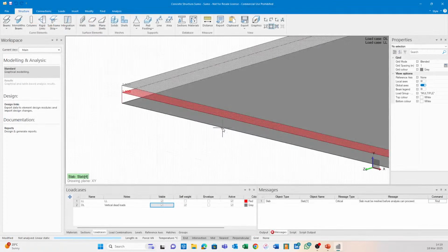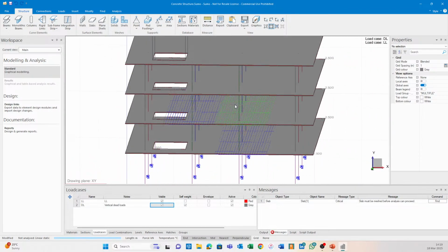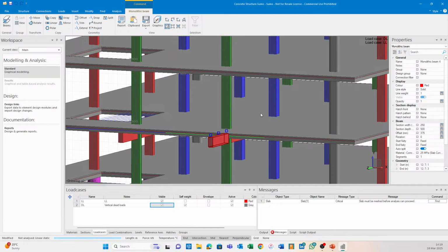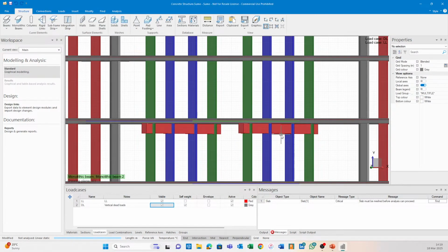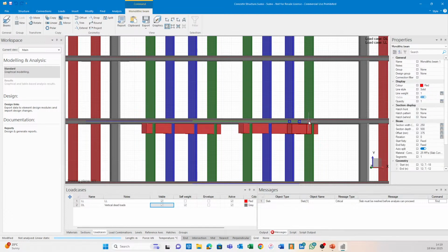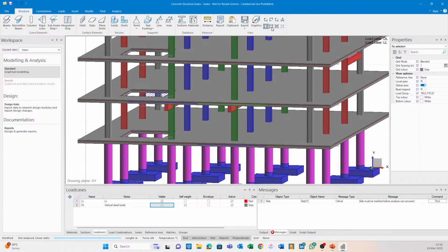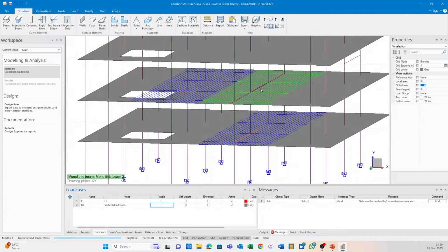What I want to take us to next is if we have a monolithic beam. So in this case, we've got two subframe strips. Now, on this side, the green one, you can see that each one of the monolithic beams is a segment between the columns. On the left-hand side, it's one continuous monolithic beam. Now, that is not a negligible point, because if I export the subframe strip where I have the monolithic beams in little segments, I'm going to pick up an issue.